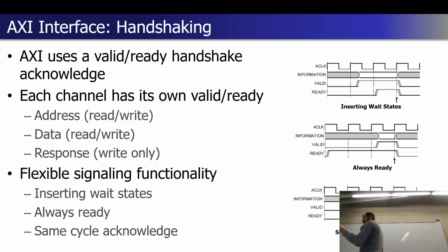So this should look kind of similar, just straight from the AXI data sheets for that handshaking. For every one of those channels, there is that valid/ready handshake going on. I think we called that command and ACK, or request and ACK, on Thursday, but it's the same concept here. The sender is going to be specifying a valid signal, and that's what valid means in ACK.